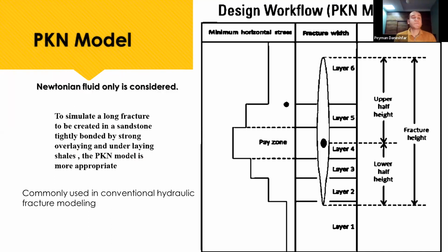The PKN model is good for simulating a line fracture created in a sandstone tightly bonded by a strong overlying and underlying shale, and the PKN is more appropriate there. For the PKN model, only a Newtonian fluid is considered.